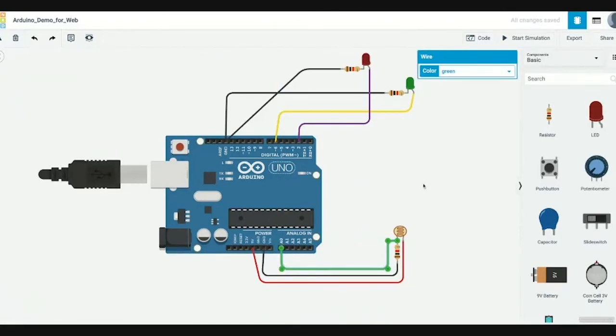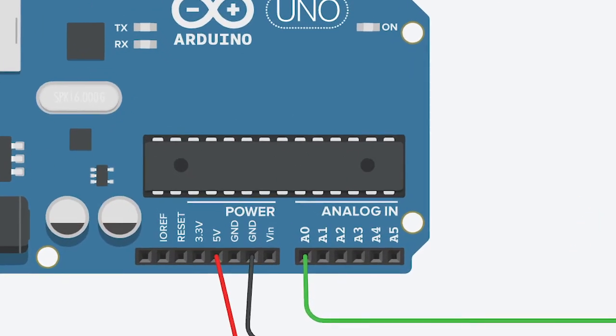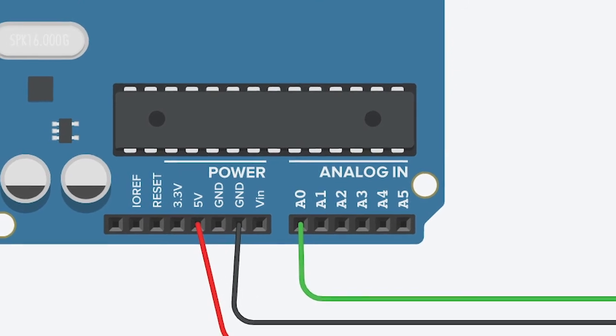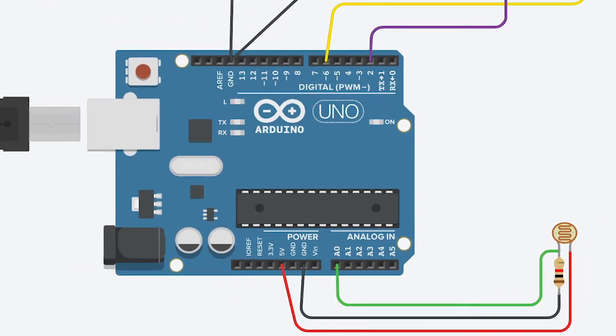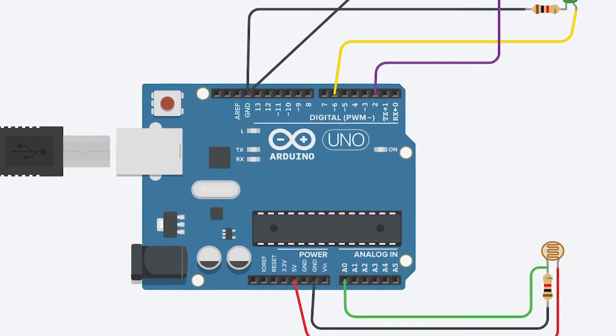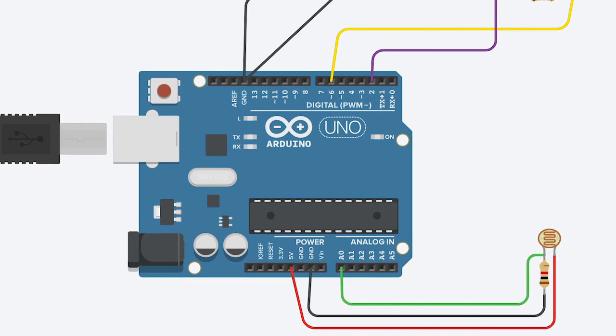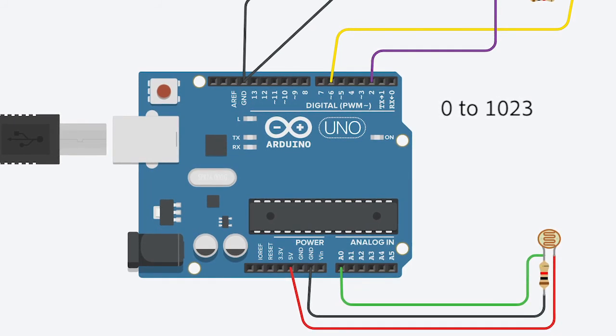Remember how we were talking about pins being inputs and outputs? Well, I'd like to introduce the analog pins. These are located on the bottom right-hand side of this board, and they're named between A0 to A5. What's so special about analog pins is that they don't actually read an on-off signal. They can actually read a range of numbers that are actually the voltage.